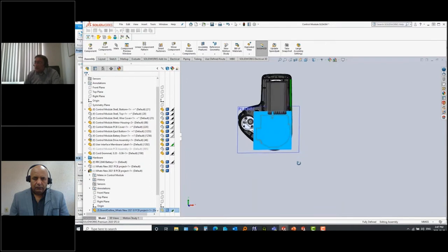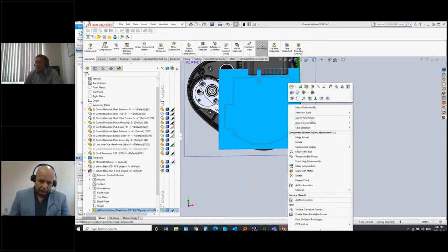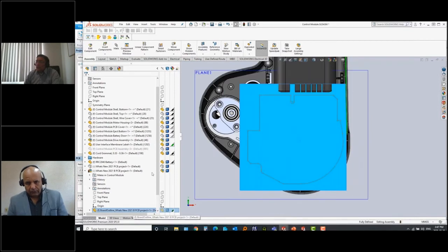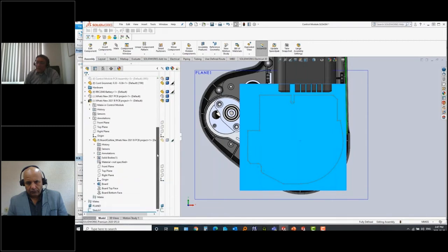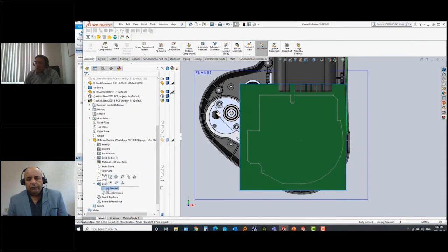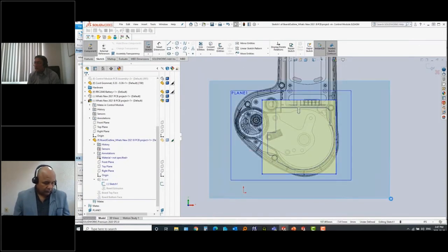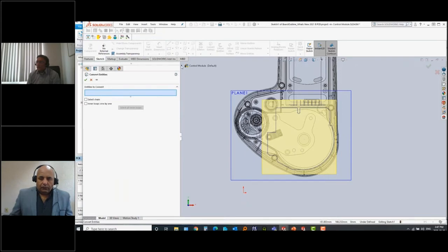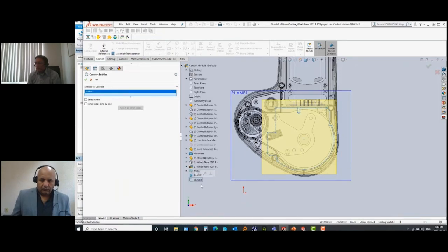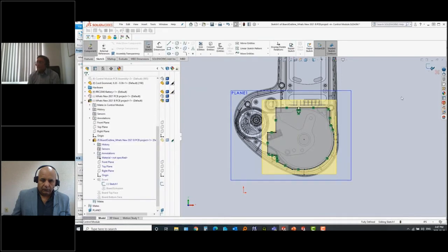So now I want to change the board shape. Again, I have lots of different options available here. There's something called the context of the component features. Here, this is the board part outline, and that comes with a sketch. The whole outline is contained in this square sketch. I'm going to change that. I don't need the rectangular one, so let's delete that. And I need a more complicated sketch, using a feature called Convert Entities, which is much easier to do here. It's no problem in the CAD environment, and I just use that as my board outline.